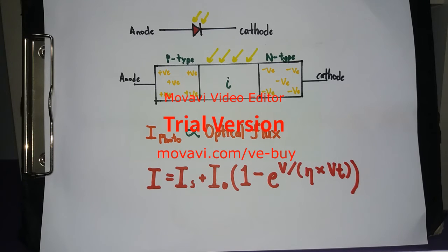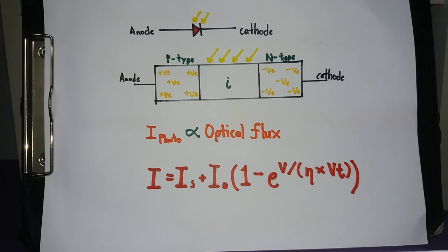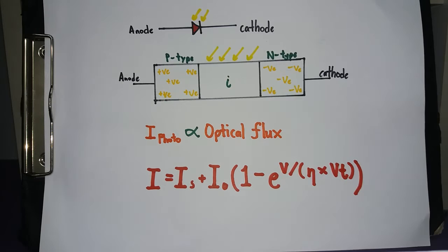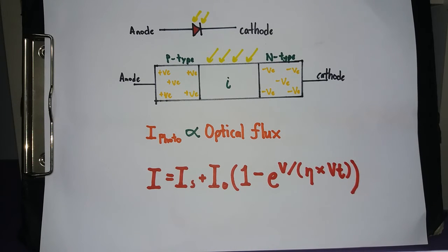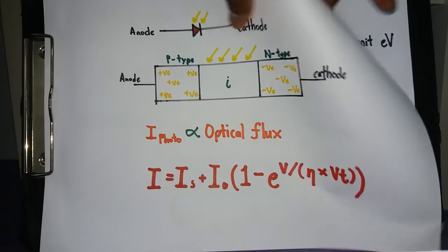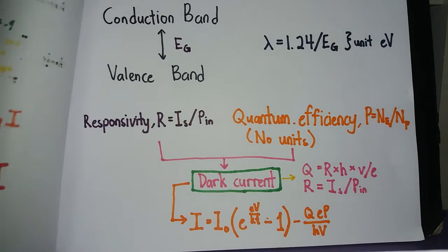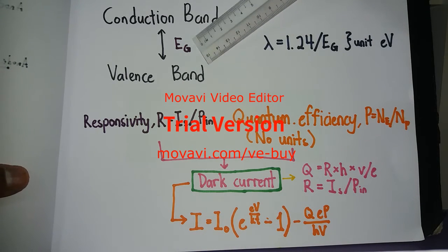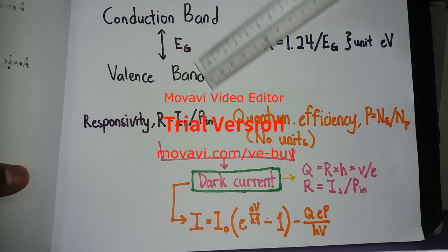A photodiode may go through two types of photo excitation, which are intrinsic excitation and extrinsic excitation. Intrinsic excitation occurs when an electron in the valence band is excited by a higher energy photon to the conduction band, while extrinsic excitation occurs when a photon excites an electron in the donor level to the conduction band, or a valence band electron goes into an acceptor state. The minimum energy of light required for photon generation due to intrinsic excitation is the forbidden gap, which is the gap located between the conduction band and the valence band.